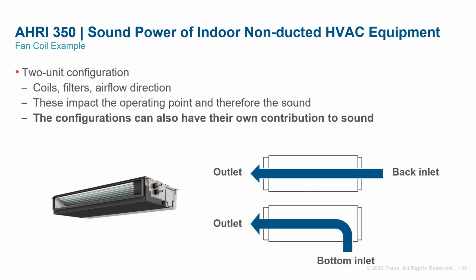However, these options can change the sound in other ways. For example, when the airflow into the unit changes directions, this can impart different patterns of airflow into the fan and alter the sound even if the operating point doesn't change. And if that isn't convoluted enough, we have unit installation to consider as well.